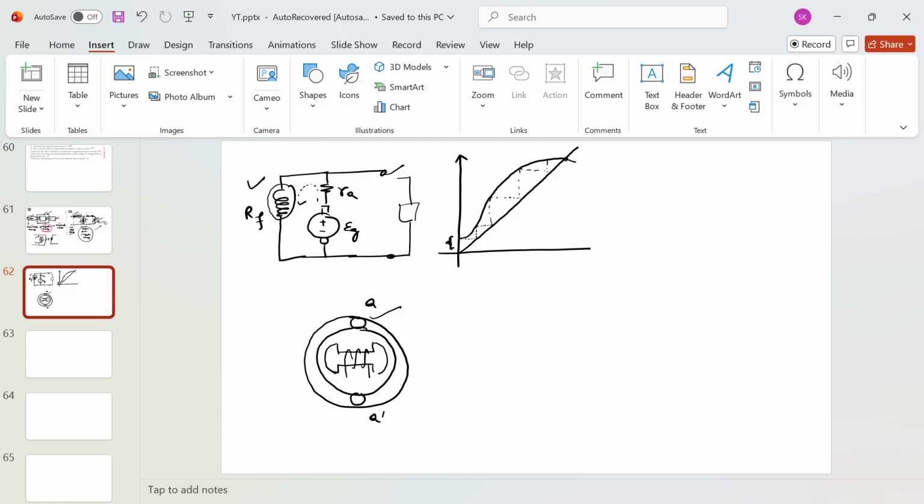A dash coils. But if it is connected to an infinite bus bar, then even if you don't give any kind of field excitation, it will draw a lagging current from the grid, and it will set up a flux, or that will create the environment to transfer the power. But in the isolated case, when the alternator is operating in isolated condition, you must have a field circuit.